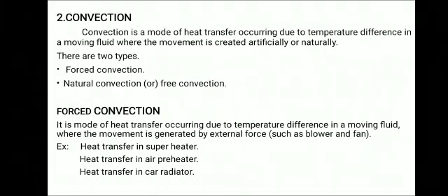The enlarged vibrating atoms touch the adjacent atoms and heat is transferred. Convection: convection is the mode of heat transfer occurring due to temperature difference in a moving fluid, where the movement is created artificially or naturally. There are two types: forced convection and natural convection. Forced convection: it is a mode of heat transfer occurring due to temperature difference in moving fluids, where the movement is generated by an external force.